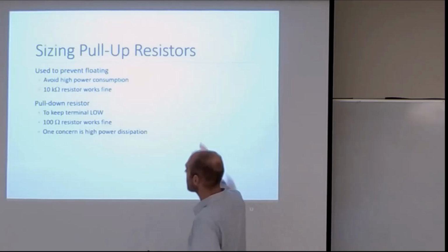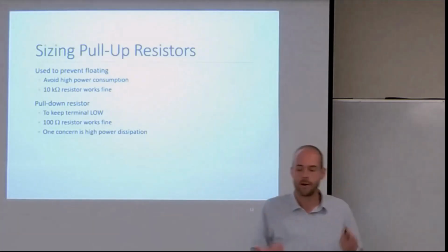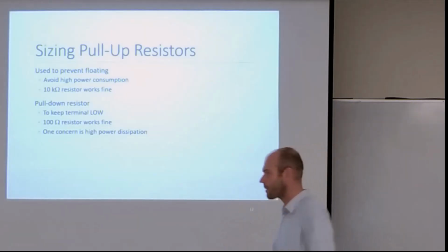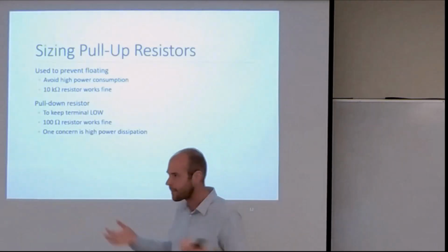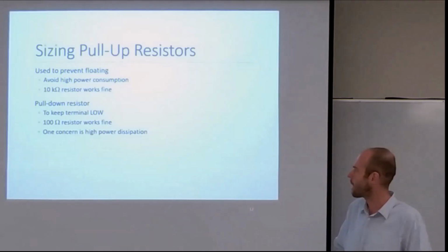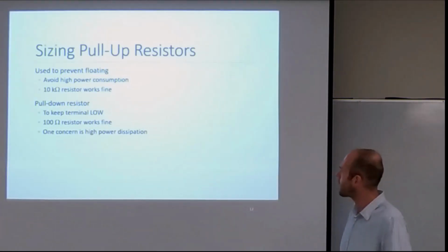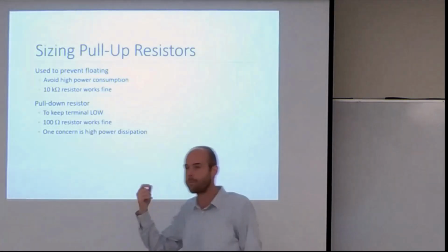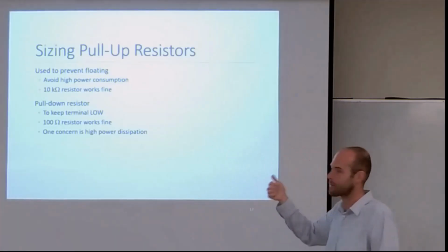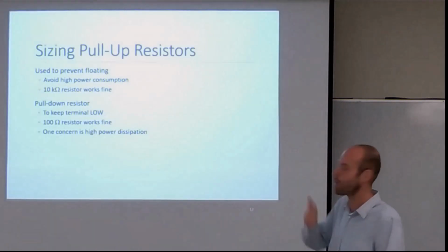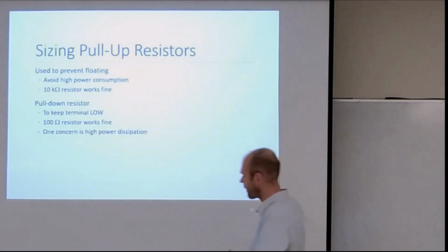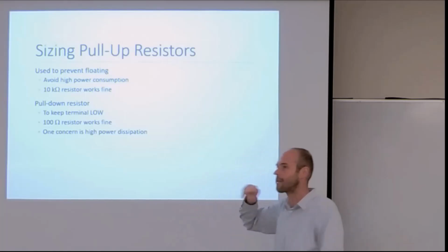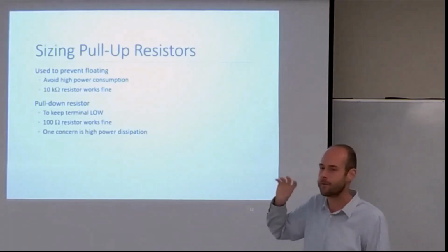Next item, just talking about pull-up resistors. We've used these all the time for various purposes. In your 179 course, for example, we talked about activating our pull-up resistors. We had them available internally on the microcontrollers we were using. Essentially, pull-up resistors eliminate floating contacts by pulling them high to your power, whatever power level you're pulling up to, which is 5 volts on our Mega systems. But activating pull-up resistors prevents or eliminates those floating contacts.